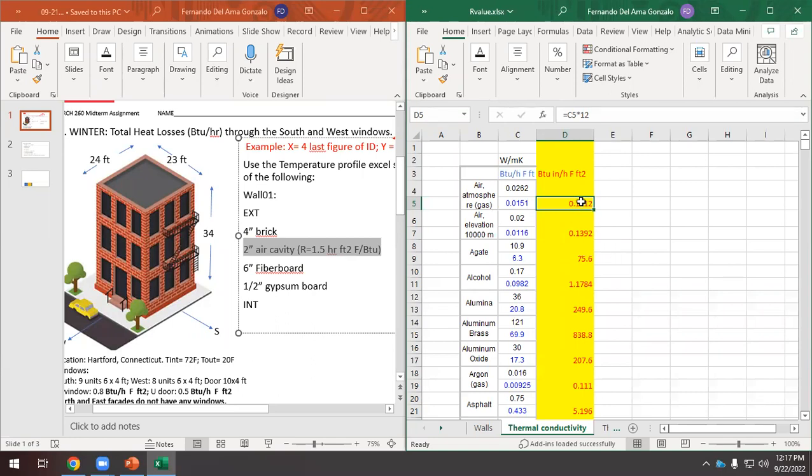But that works. So this thermal conductivity for air works when we have a non-ventilated air cavity or chamber. For example, in glasses, here we have glass. We have 2 panes of glass, or 3 panes actually, and we have 2 air cavities here.